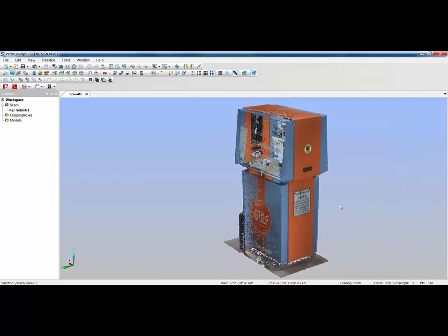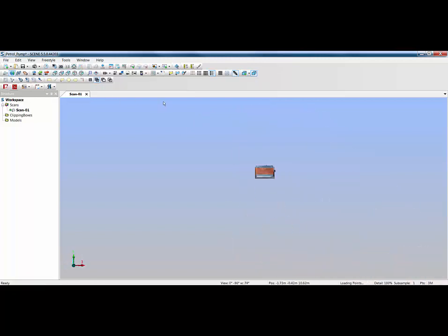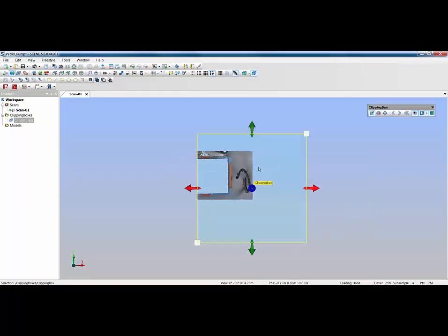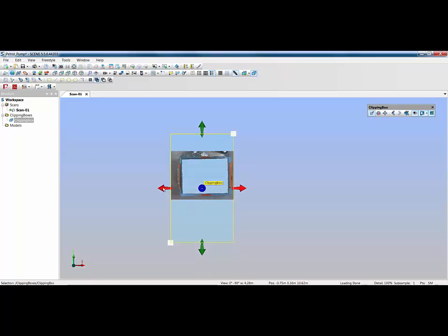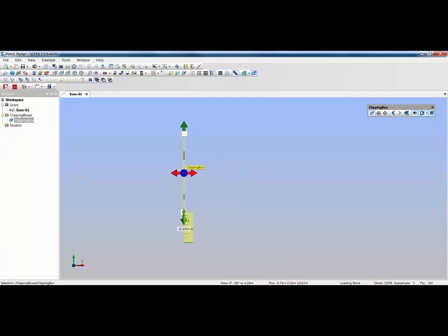Before I do that, what I'm also going to do is show you some multiple sections. Same as before, if I look at the pump from the top, we're going to flip into an orthographic mode, and then create a clipping box over the top. I'm going to get this nicely lined up and put the clipping box roughly in that position there, take a slice through my data, and narrow in these sides. If we rotate, we can make sure that we're picking up the top of the pump like so, and then we'll pull up the bottom.